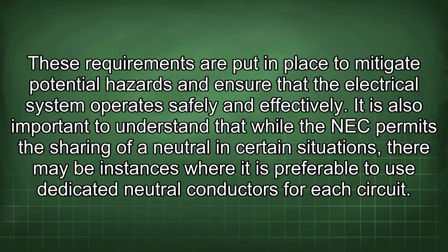These requirements are put in place to mitigate potential hazards and ensure that the electrical system operates safely and effectively. It is also important to understand that while the NEC permits the sharing of a neutral in certain situations, there may be instances where it is preferable to use dedicated neutral conductors for each circuit.